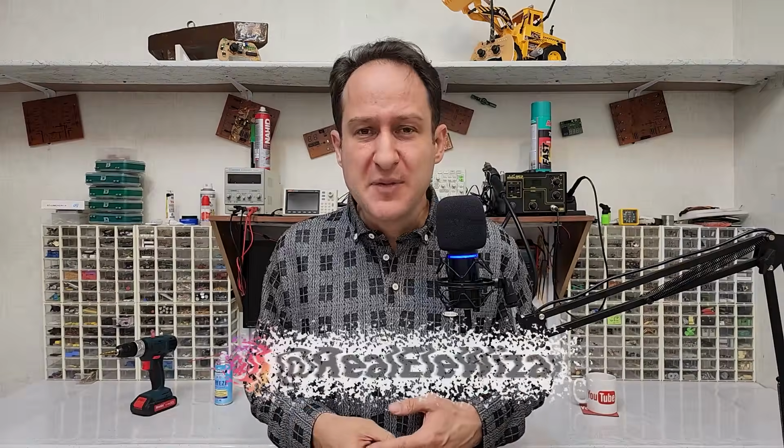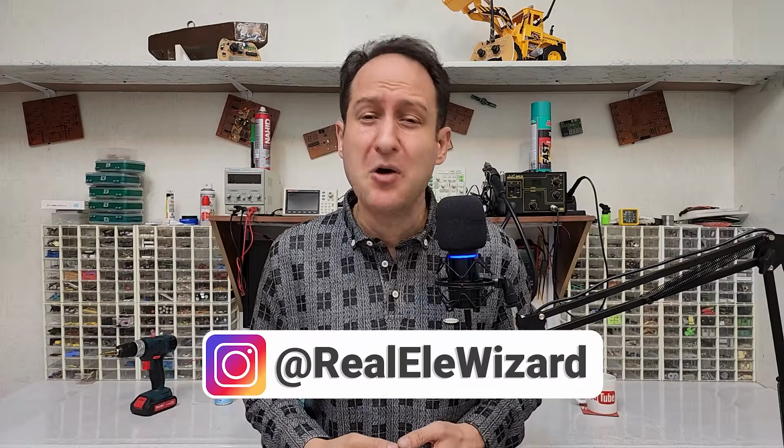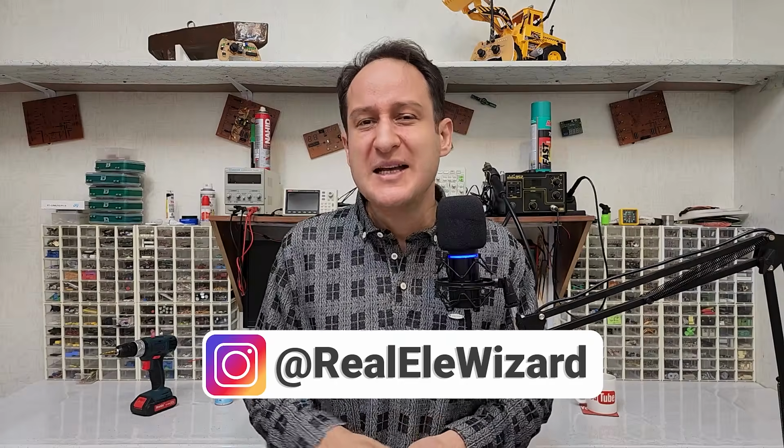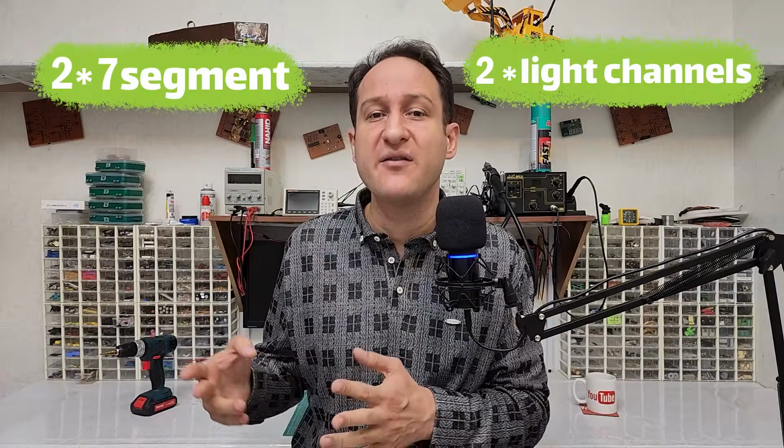These drawbacks led me not to use the multiplexing method in the 10-channel lighting system project, and instead I used a different method that doesn't have these issues. Oh, by the way, I forgot to mention that this video you are watching right now is part 4 of the 10-channel lighting system project with an infrared remote controller, which we did using an STM32 microcontroller. In that project, we used 4 74HC595 ICs, 2 for 7-segment displays, and other 2 for driving the channels.